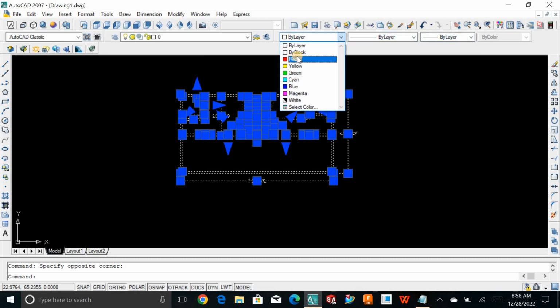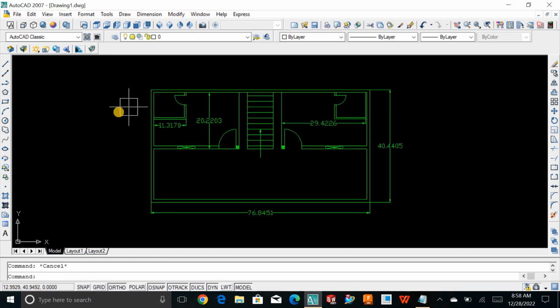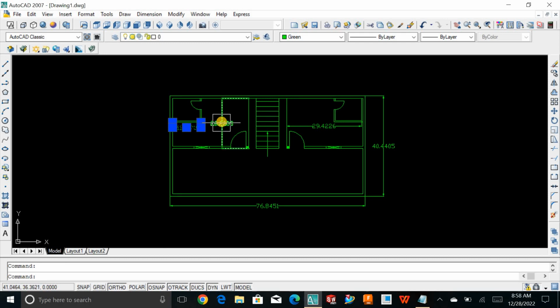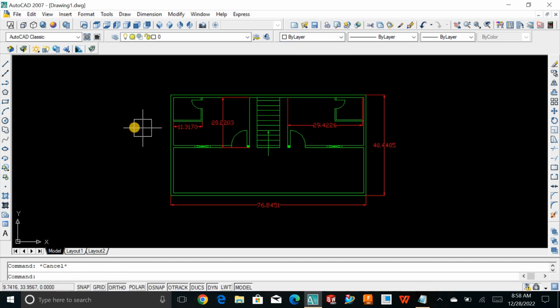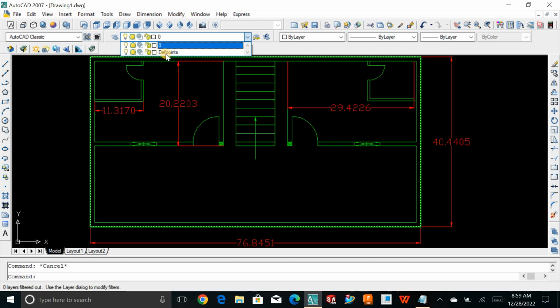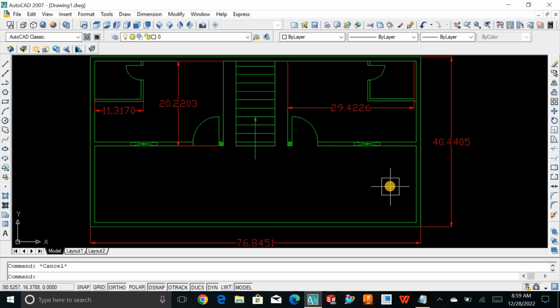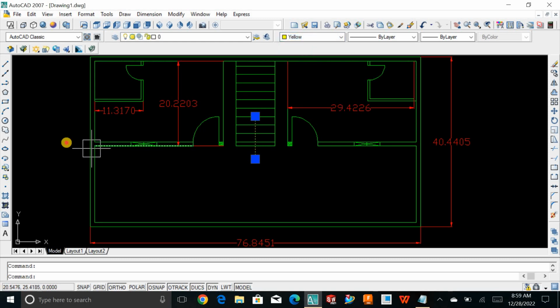And by layer, I just want to talk about this one. See, now it just looks pretty. I will choose this, press and hold, like choose all the dimensions, go to by layers and choose them red. You can define the different layers creation from here as well, but for now you can create the new layers and define the dimensions in one layer, defining the drawing in other sections. And I just wanna go for this, and we'll just define yellow for now.